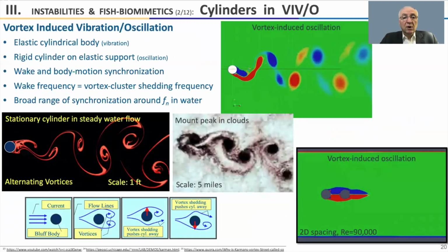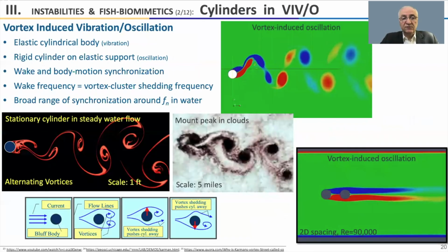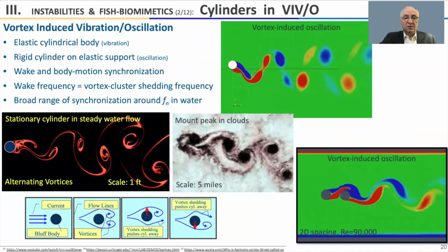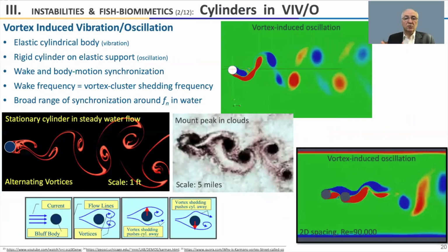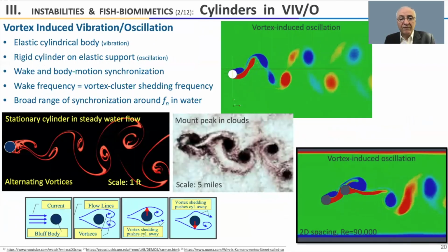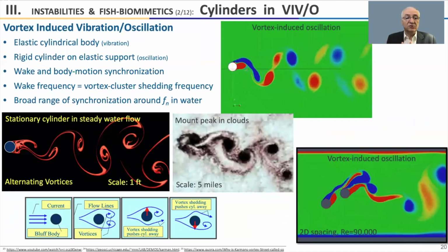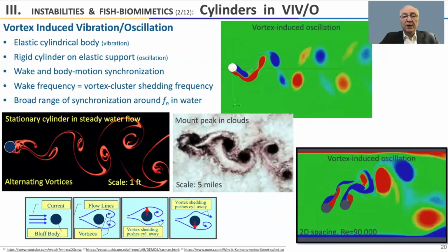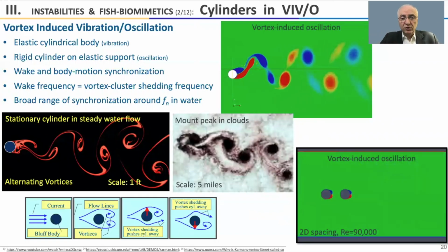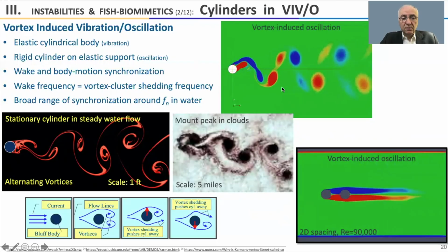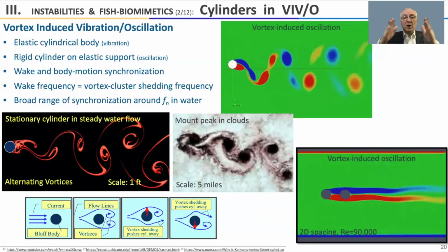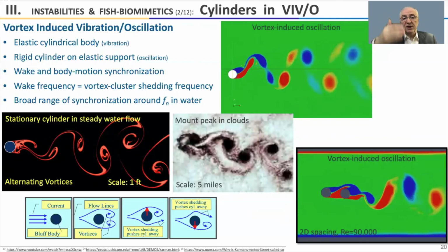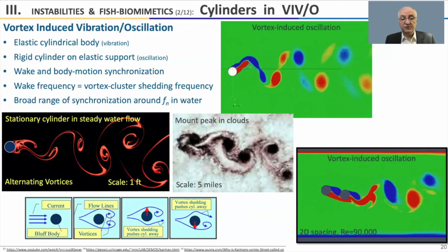Now, let's talk a little bit about vortex-induced vibrations, even though most of you know about it. Whether you call it lock-in or synchronization, or as we proved last year, we have an eigenrelation that the oscillating cylinder has to follow, you are talking about an alternating lift force, alternating wake, and you are talking about a very broad range of synchronization over which the cylinder has large amplitude of oscillation in spite of the change of the inflow velocity.